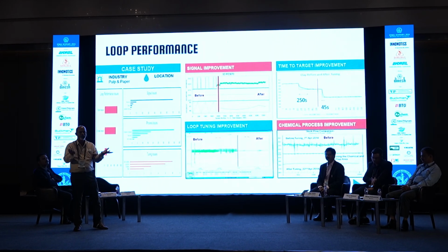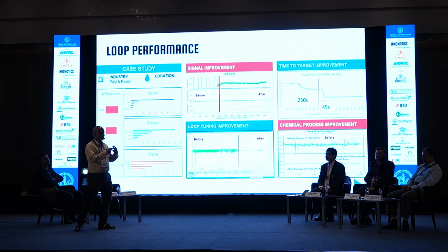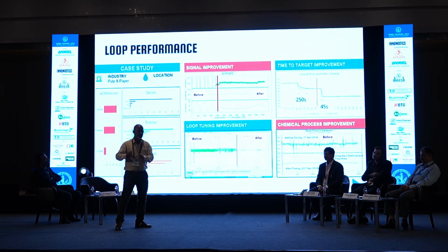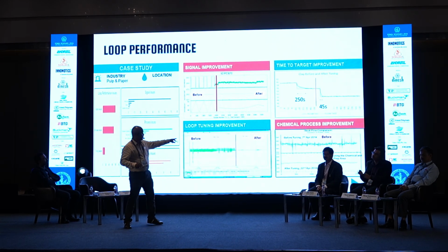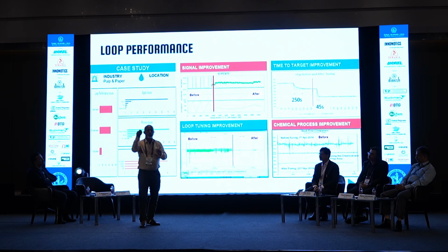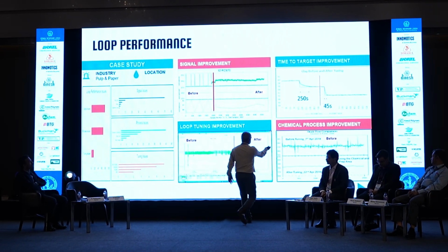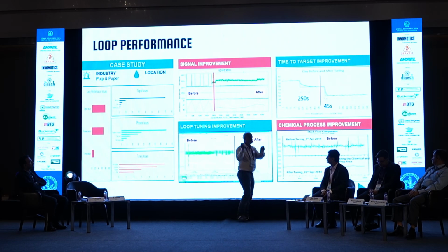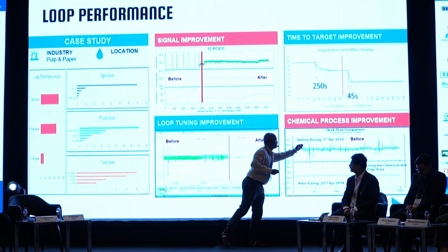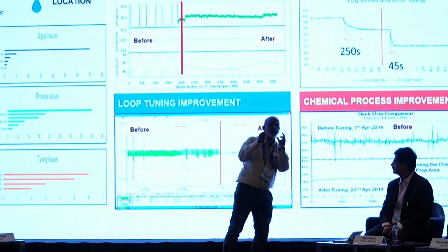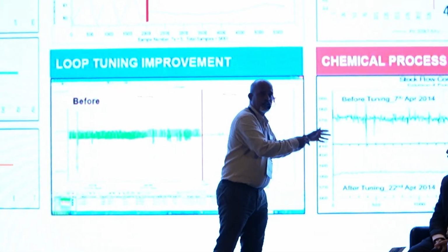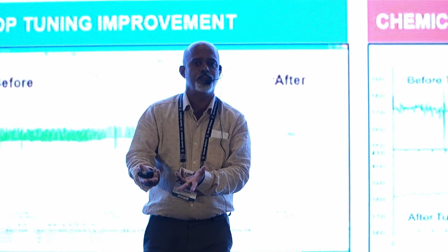So there is no tuning possibility, because I calculated the number and put that number in. There is no possibility. But if you see here, they introduced one chemical. That chemical created this stock flow, before tuning and after tuning. The chemical created some spiky measurements. When you have spiky measurements, it's not real. It's a spike induced by the chemical.